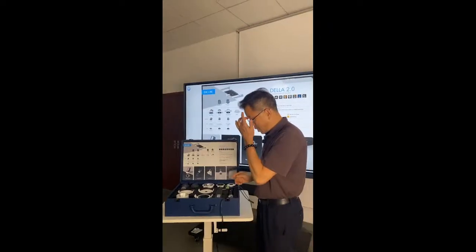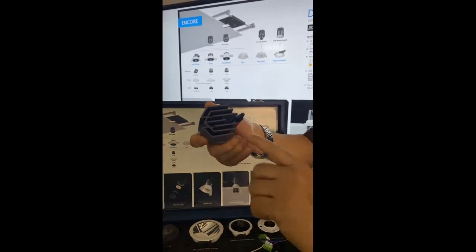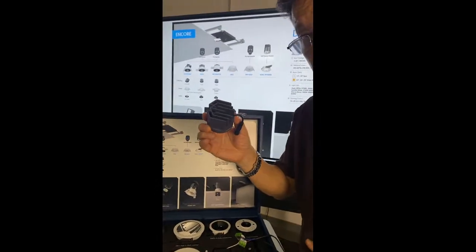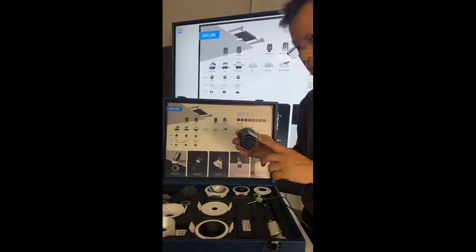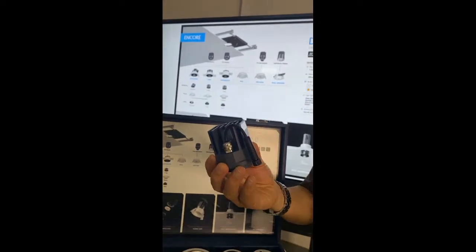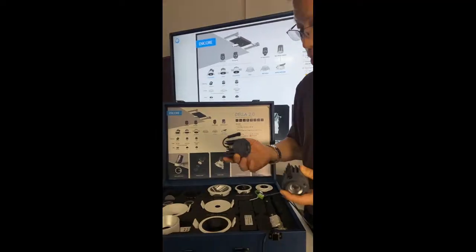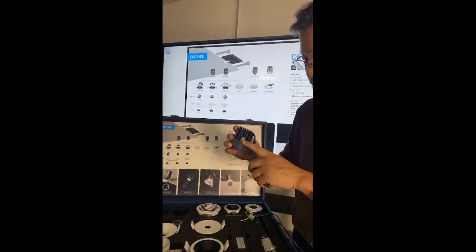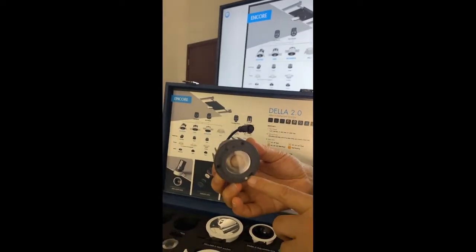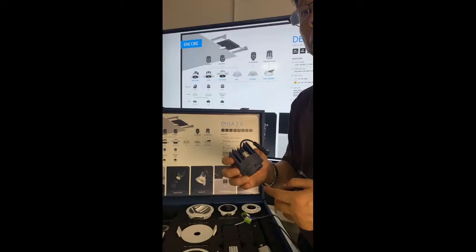For example, here is an LED engine, right? This is the logo of Encore. This is IP20 LED engine. Here is IP65 LED engine. Any difference? Of course. For this IP65, we use a gland connector. And we have O-rings inside, the optics. And every part is fully sealed, so it can be IP65.